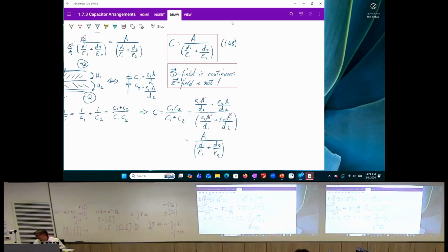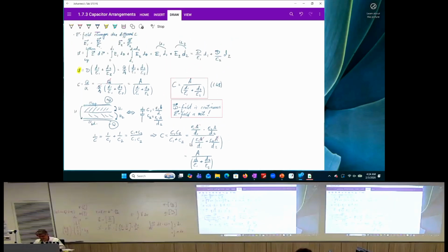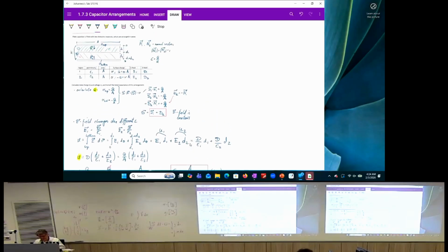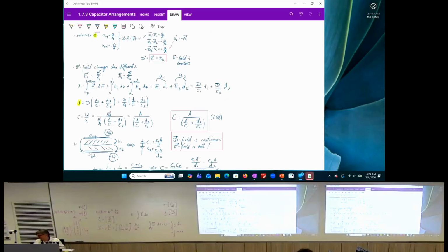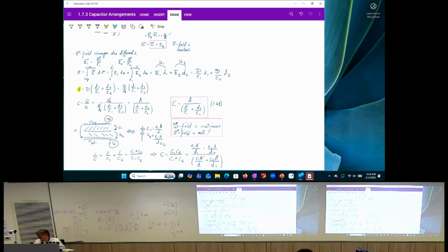And now if you compare it to the formulation that we have derived, you see that it is a perfect match. So we see that this confirms that we can represent this parallel plate capacitor, which has two fillings on top of each other, so not next to each other, but on top of each other, as a series of multiple capacitors in that equivalent circuit.